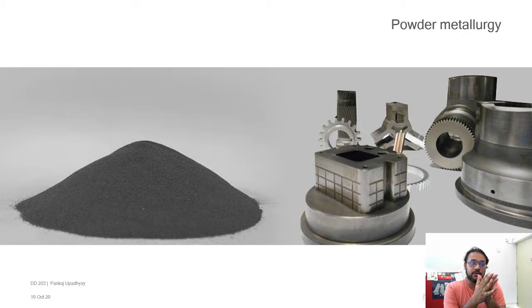You could mold the part that you want, then take it through the necessary chemical paths, and put it in an oven to remove all the plastic. One of the processes that we discussed was something called sintering, which basically the idea was that after the plastic has been removed from such an injection molded metal injection molded part, the sintering process heats up these small granules of metal and melts them just enough so that they can fuse together and form a homogeneous solid part.